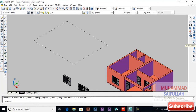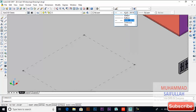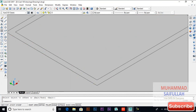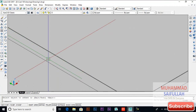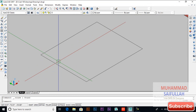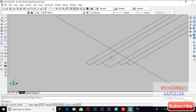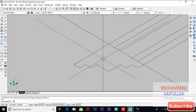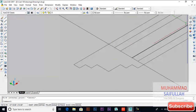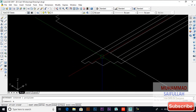Now I'll switch back to southwest elevation isometric view, and I will select line type again by layer, I mean by sample. I will take offset inside of 18 inches because I will have to create a shade here, so that's our boundary for the roof, and the rest of the 18 inches will be our shade. So I will extend these lines, I will trim it, boundary, pick points, I will pick an internal point. So if this error comes, you can switch to 2D wireframe, BO for boundary, pick points, click here, enter, and move this.